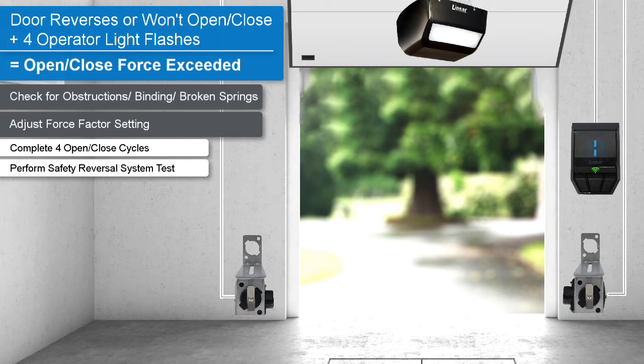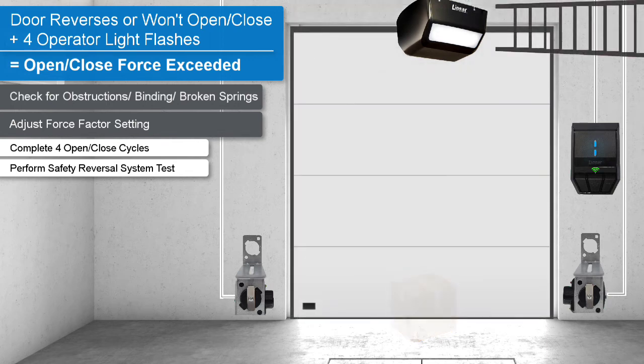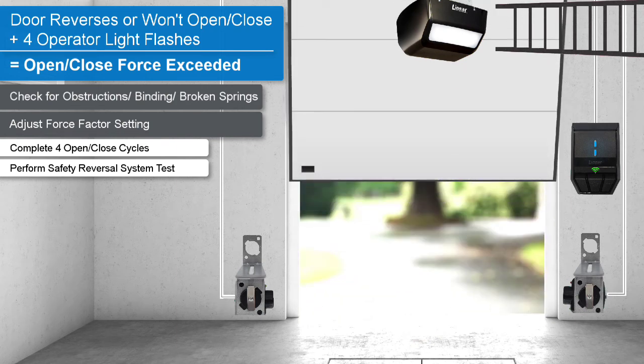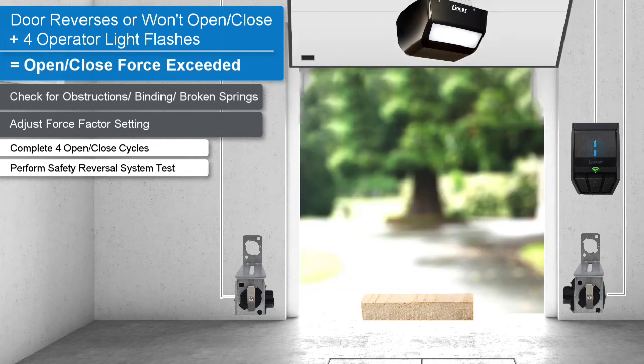The safety reversal system causes the operator and door to stop and then fully open if an obstruction is encountered during a closing cycle. If an obstruction is encountered during an opening cycle, the opener and door will simply stop. To perform a safety reversal system test, lay a 2x4 board flat on the floor where it'll be struck by the center of the door as it closes. Verify that the door reverses when it strikes the board. The door must reverse within 2 seconds after striking the board.